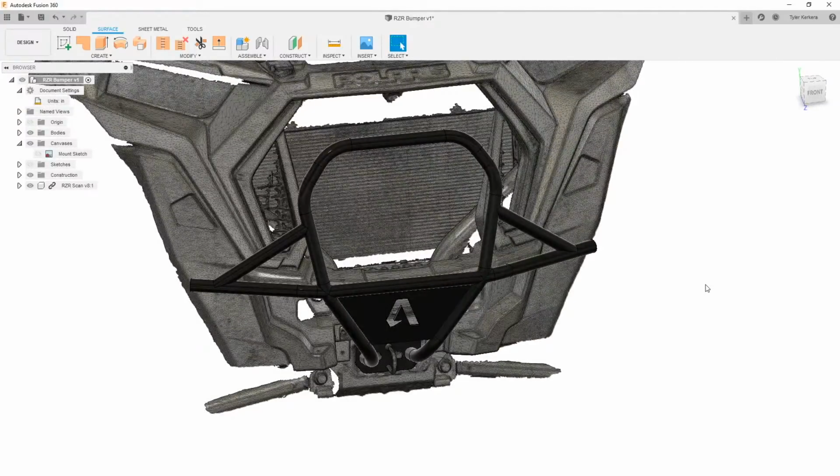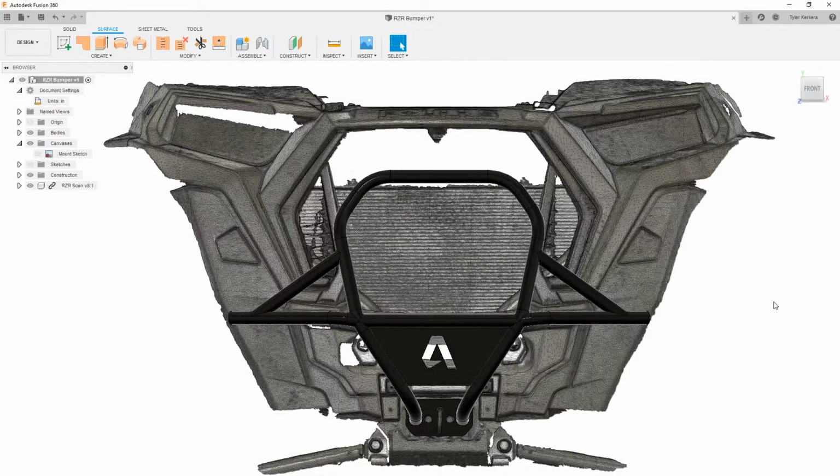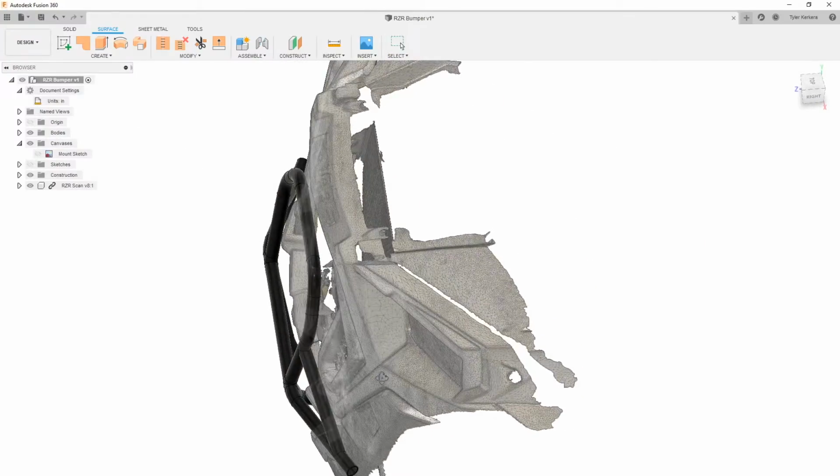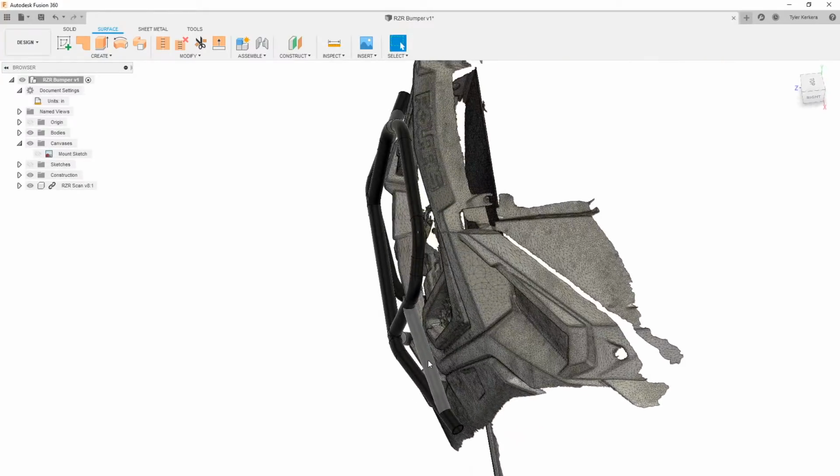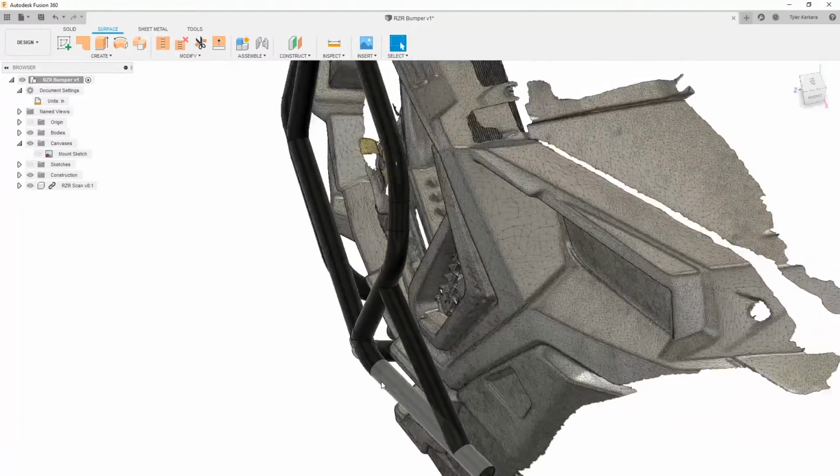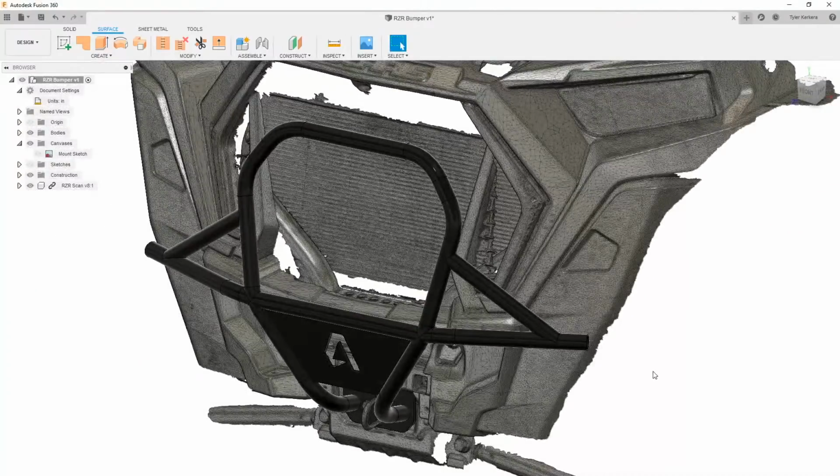And again, at this point, really the whole intent of having this mesh behind it is without having to go out with like a measuring tape or physically have to touch anything, I have the exact bodywork of this really, really complex design already here that I can immediately reference. And yeah, I wasn't taking any direct measurement off of it, but I was creating some like aesthetic lines connecting like one piece to another. I can also see now that, oh wow, yeah, you know what, this is going to be a perfect clearance in between this bodywork here and my bumper. I don't have to go through and practically make this and then realize, oh, you know what, this support member, it's at the wrong angle. Let's go back and scrap that entire design and start over. Here, I have it, and it works.